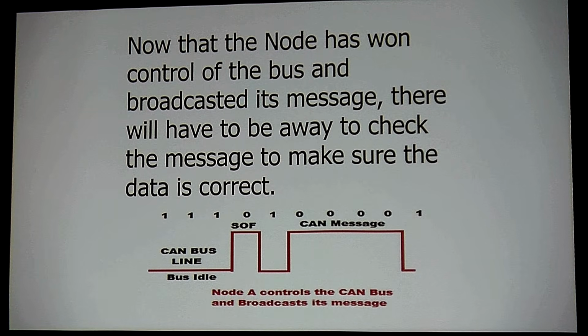The latency on your scan tool, guys, is the lowest, slowest, just the way it is. So when you think of that scan tool and those dots that I put together that look like a scope, that ain't no scope. It's hard to say how much latency is between each point. The more values you choose for your parameter identifications, the longer your latency is. So if you have something quick, don't have 10 PIDs picked, because I've got to arbitrate for every one of them. So when you say that you want a MAF, I arbitrate for the MAF.